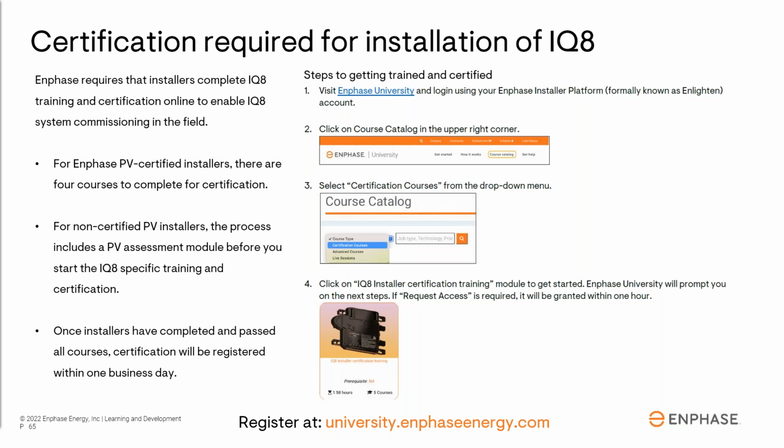So for those of you who are going to be installing IQ8s or already installing IQ8s, it's important to note that you have to have an additional certification from Enphase in order to use the software to commission a system. I'm going to share this PDF deck with Jill so she can share it with all of you, and it will have these instructions to follow if you need to. Essentially, you have to take the standard Enphase storage installation training and an IQ8 training course. Because as we reviewed today, there are some additional components like the Enphase system shutdown switch and some other installation details which are important when installing IQ8s that didn't apply to earlier models.